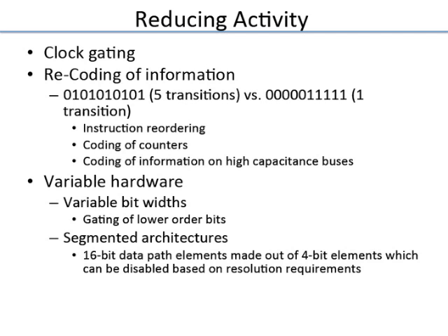Not only does it reduce the activity in the clock signal, but all the flip-flops to which this clock is connected, their outputs will also be frozen now, because they will only change when the clock is there, and those flip-flops feed all the combinational gates. None of them will have activity. The whole block will have no activity. So that is a simple technique which is widely used.